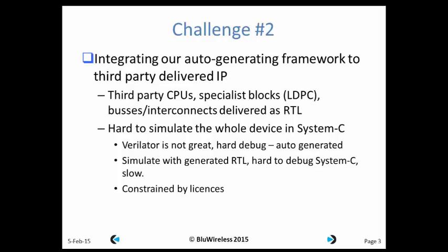Well, one thing we can do is we can verilate. So we can take the RTL and try and go back to SystemC. That doesn't work very well because it's an automated process, and it's quite difficult to debug because you lose meta information as you go between the two states. And similarly, if we go the other way, we take everything to RTL, it's very difficult to debug the SystemC side that we've written for our own IP blocks. So that certainly has been a very big challenge for us to put that together. And of course, the whole thing is constrained by licenses. Certainly, C to silicon is not a particularly cheap route.